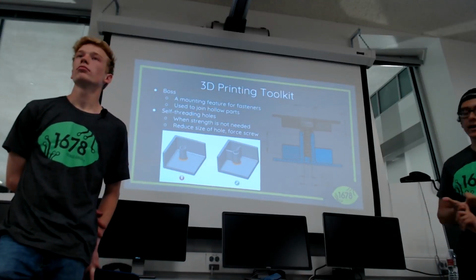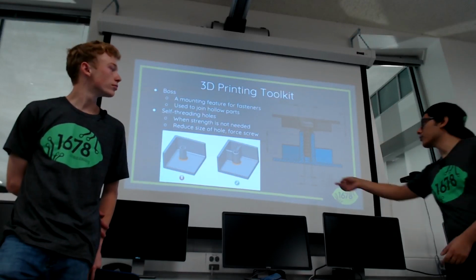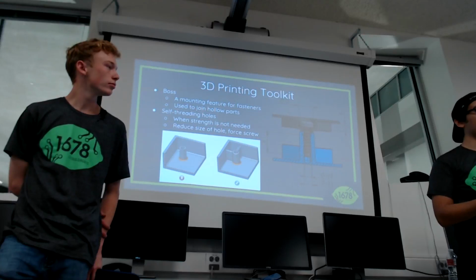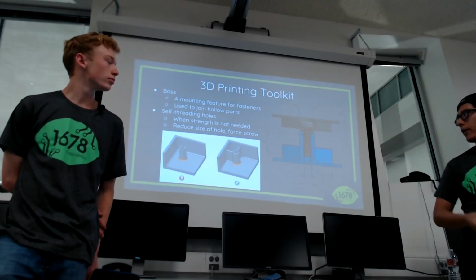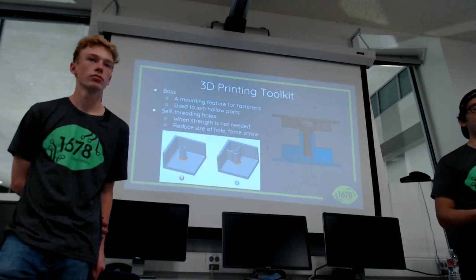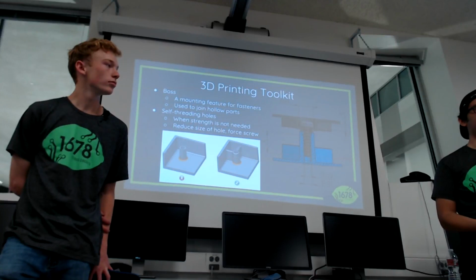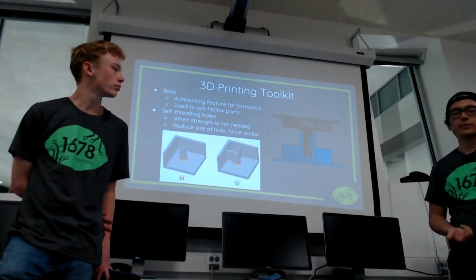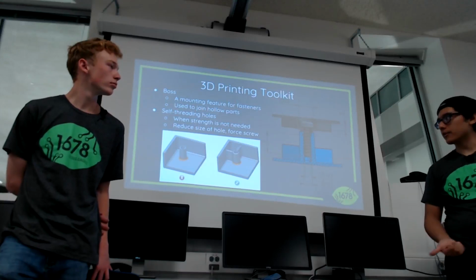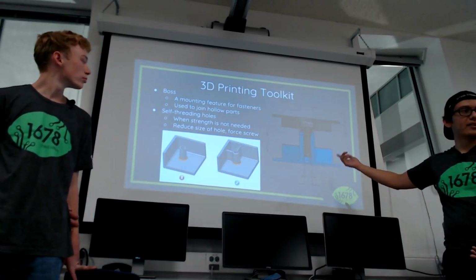And then something to keep in mind is the hole sizing. Normally, when you're creating the hole, you just go for the internal diameter of the bolt, the smaller diameter. But because of the hole shrinkage, you'll probably have to play around with it and up the size a little bit. Typically, you aim as close as you can to that. And then you use a sheet metal or self-tapping screw, and those will cut into the plastic itself. So our boss is the actual feature that comes up, and then you thread a screw into it.